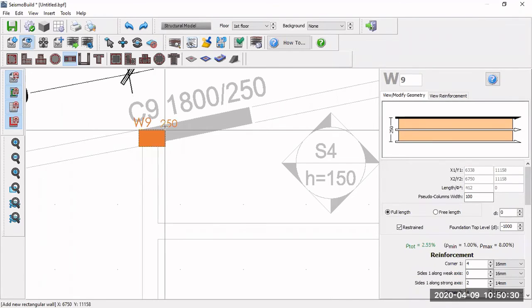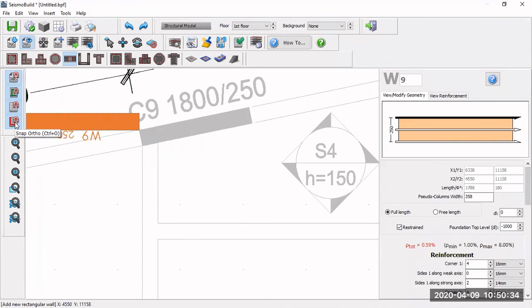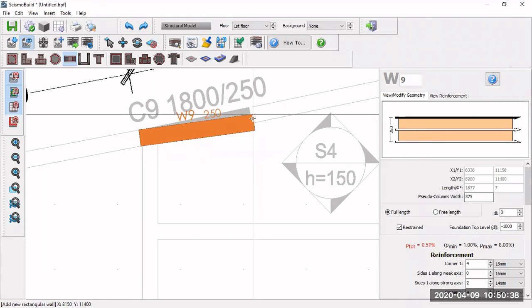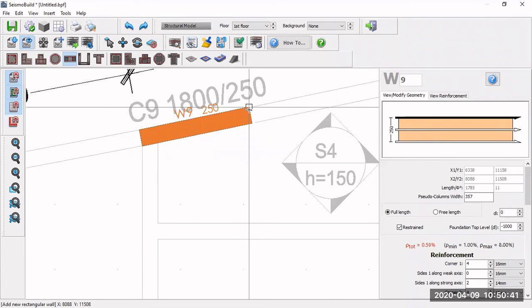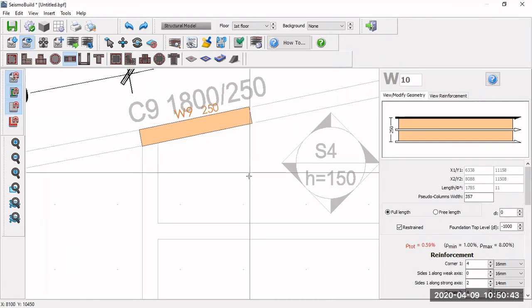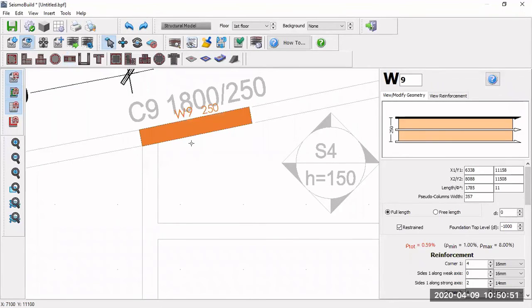All right. Then, because you notice that I already selected this, snap to auto is on, so I switch it off. Then it will be following the line here. So we can select the next line. You click. This is how you insert the wall. It's very simple. All right. So if you select this select element button here, you go to select this wall. These are all the properties in the wall. You can double check again if you want to.